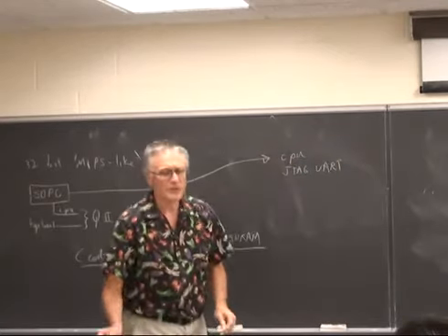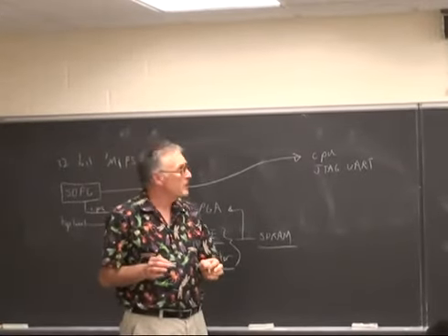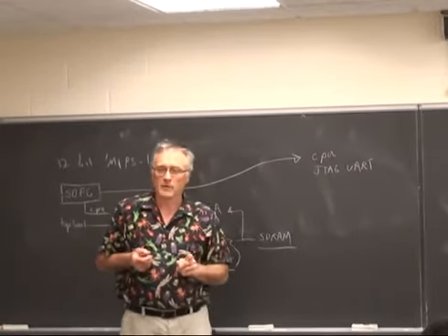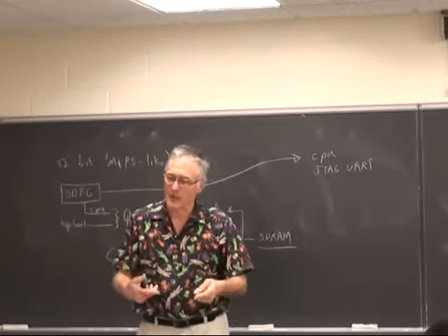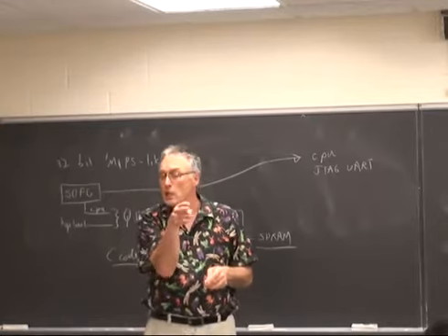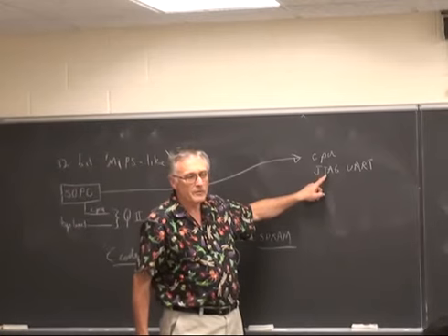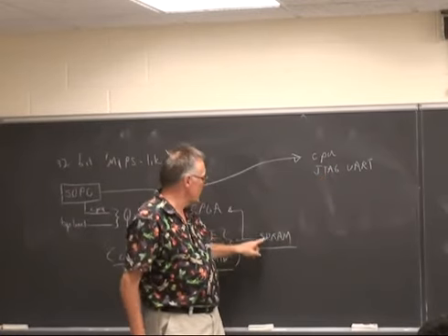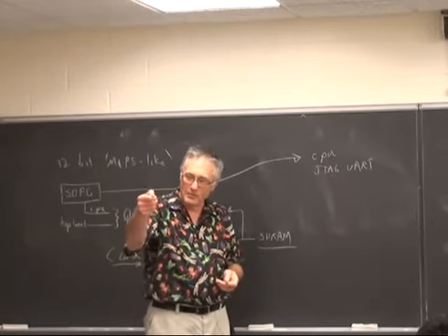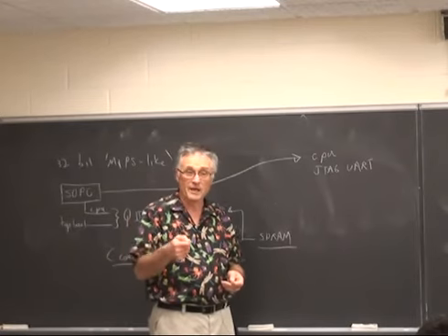This is a very special and somewhat weird I/O device for the CPU, because it allows you to communicate serial information from a high-level construct like a printf, through a secret channel inside the CPU, through the JTAG cable that you use to program the FPGA. So there's this weirdness that the same cable you use to program the FPGA becomes the serial communication to the CPU.